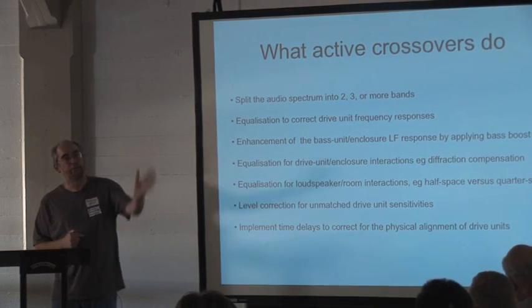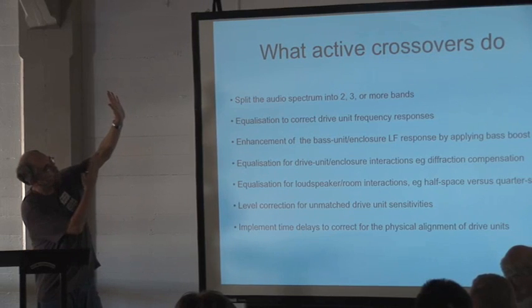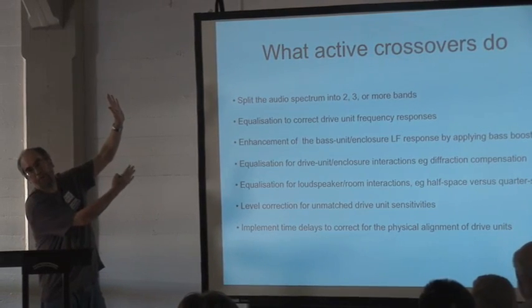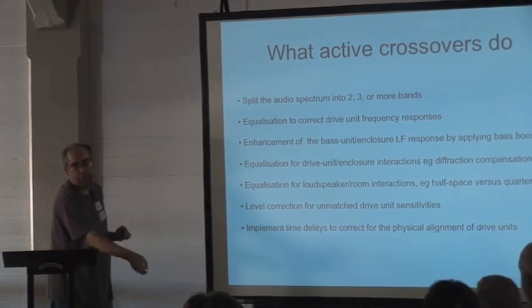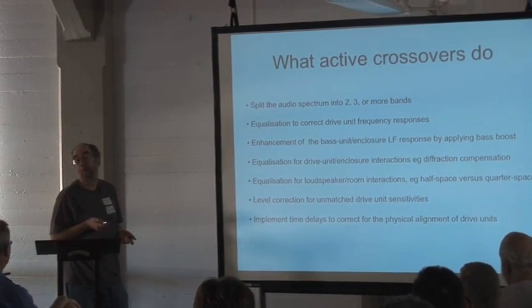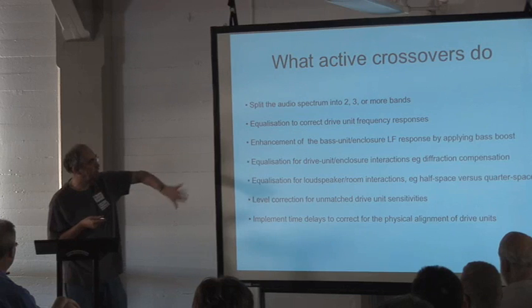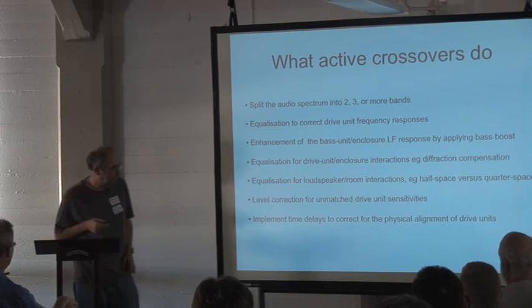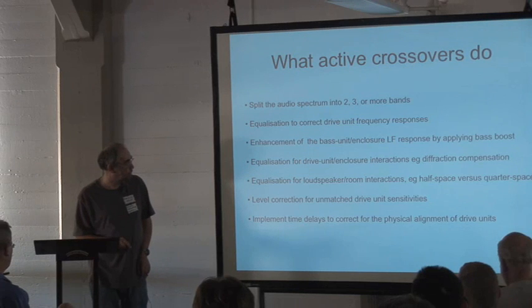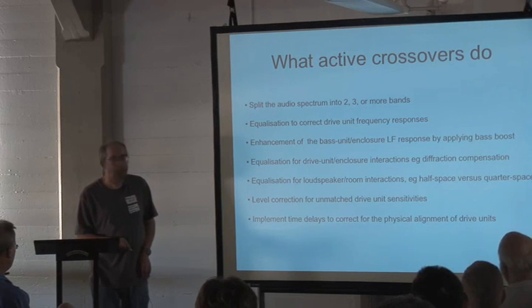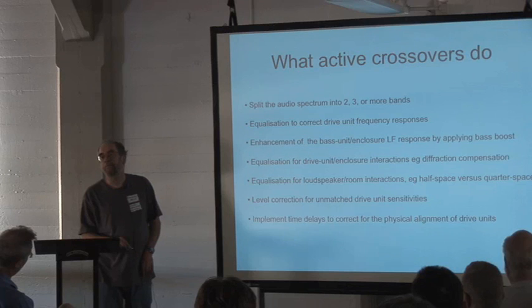Because normally you've got your tweeter there, and the acoustic center of the LF unit will be further back. Unless you've got a stepped front on your loudspeaker enclosure, which brings in lots of extra problems, of course, because then you've got diffraction around the step, and flat is really easier and cheaper to make. So what you need to do is to delay the signal going to your high frequency unit.